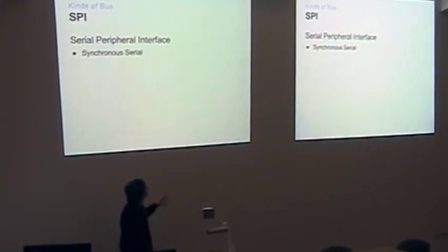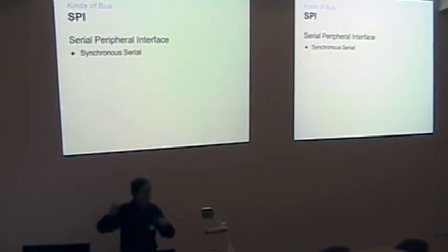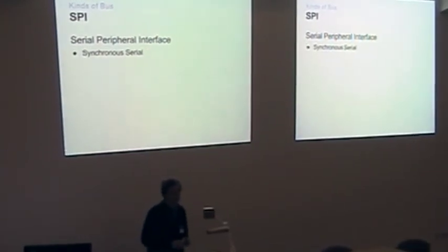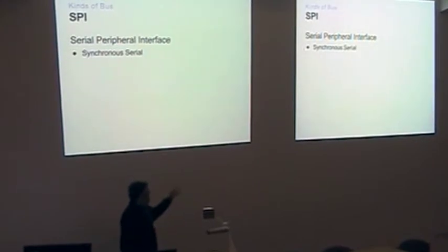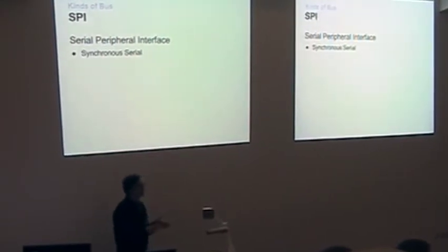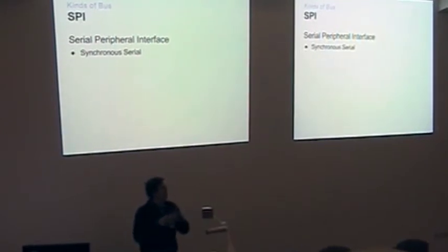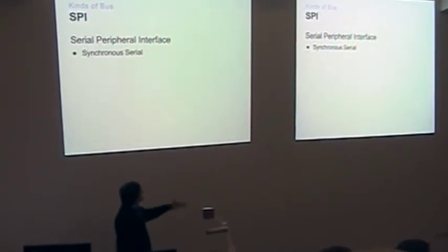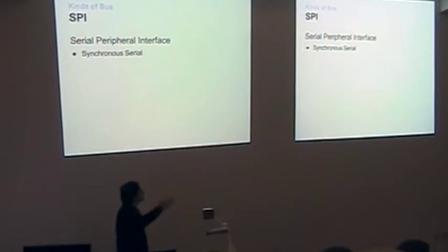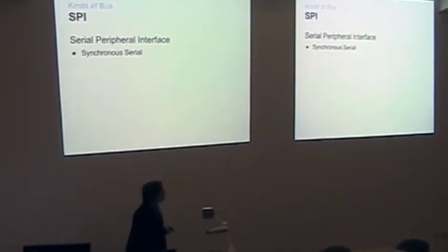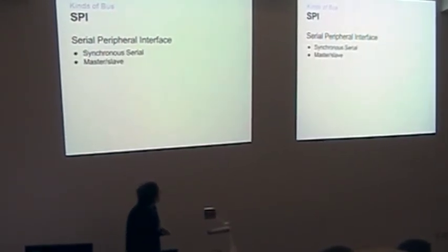In hardware terms, synchronous and asynchronous mean something completely different to how we might consider them in programming terms. What synchronous means in this case is that you have a clock pin that sends the timing information with everything else, so that everyone else doesn't need to have accurate timing. They pull the clock off the wire. I'll show you that fast in a minute.